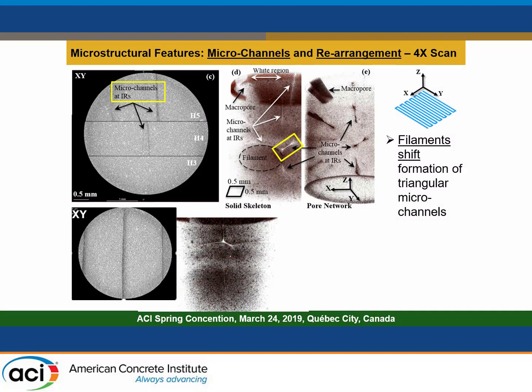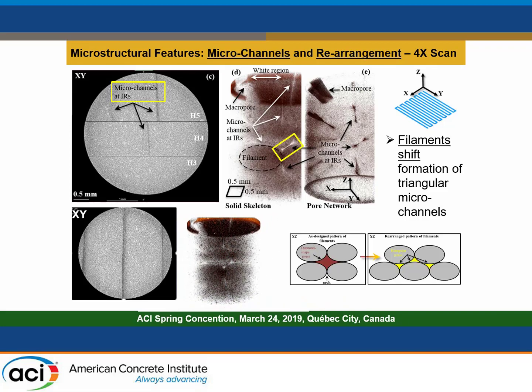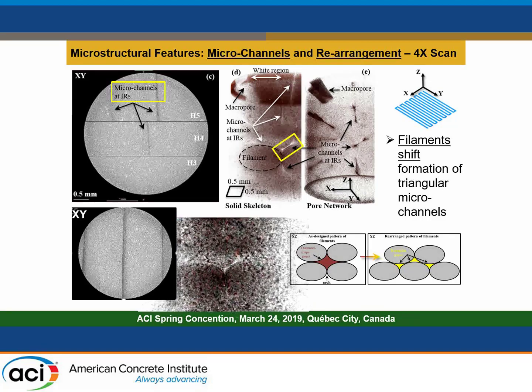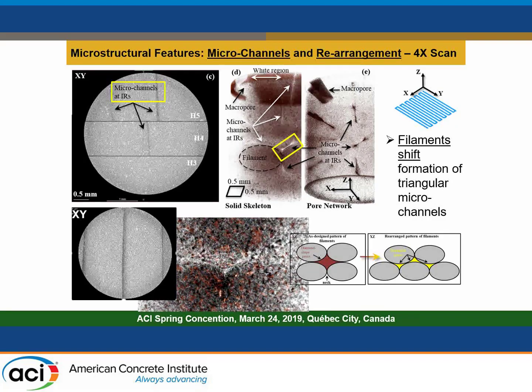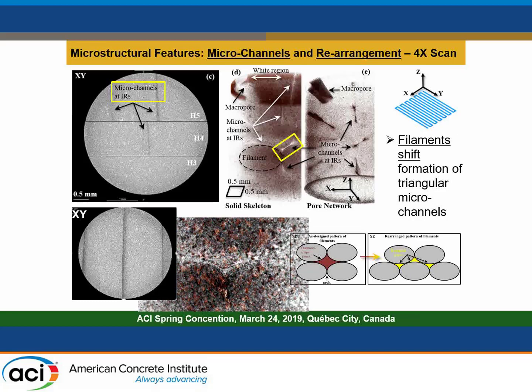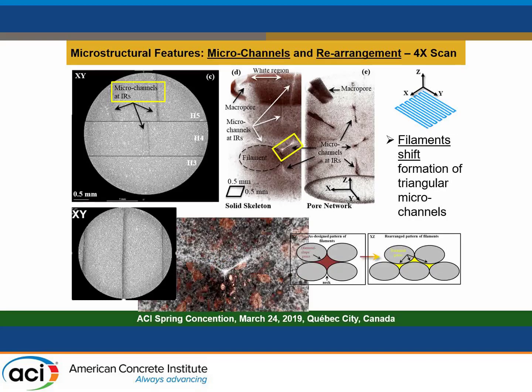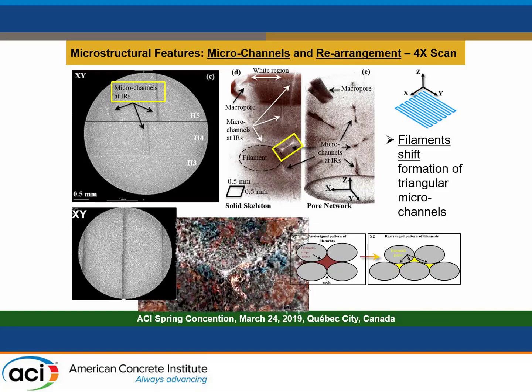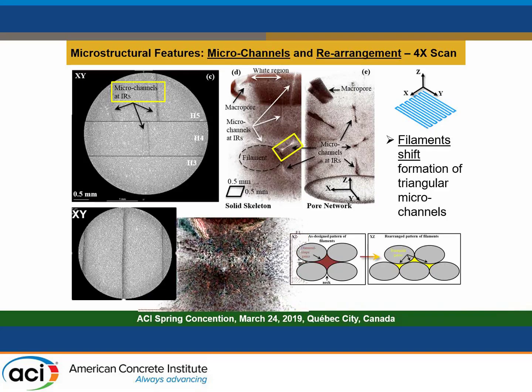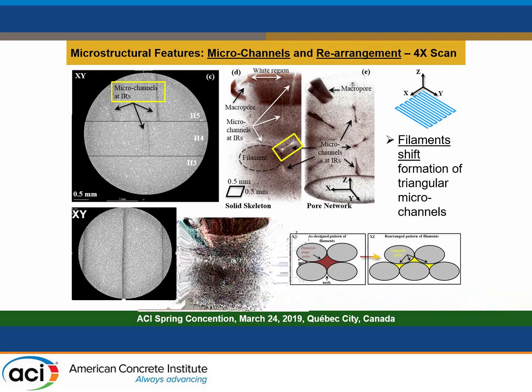You can see it more exclusively here, and that influences the internal porosity. That changes the nature of these interfacial zones. If you look at this as a close-packed structure, from this diamond type of opening to more of a triangular form of openings that you see over here. And interestingly enough, you don't actually see that on the outside of the element.